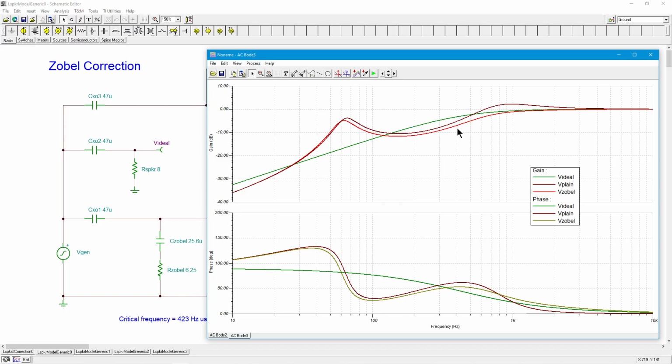write home about. As a matter of fact, this area right in here, 200, 300, 400 hertz, is actually a little bit lower than we would like it to be. That actually made things a little bit worse. Now, again, if you had maybe a third order crossover, this wouldn't be quite so apparent. That's, again, why I'm using the first order here, so you can see all of this. Similarity in phase shift, it's not like a huge improvement down here, but there is some improvement.